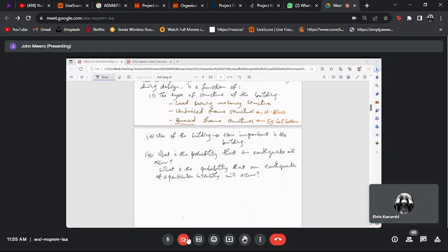Okay, so that's a good question. I've just mentioned this in passing, but if you look at any of the standards for earthquake forces on buildings, there are several considerations to say how important a building is. Of course, the first and most important is human life. So you'll find that structures that are likely to house many people, places where people are likely to congregate, like schools, like public buildings, usually have a very high categorization in terms of how important a building is.